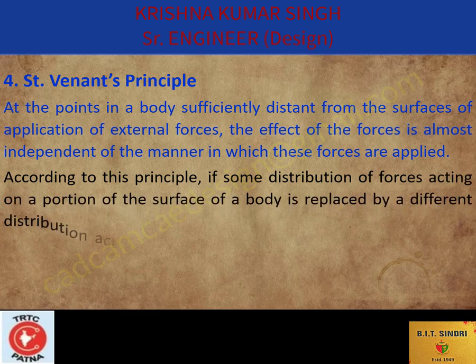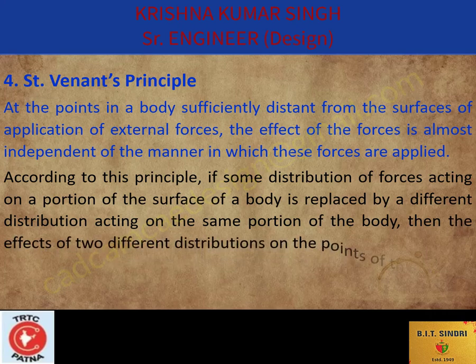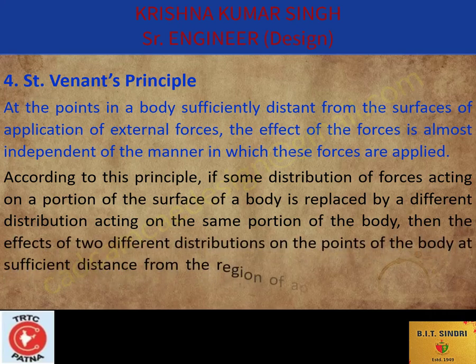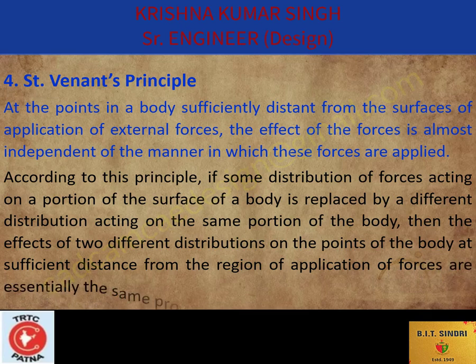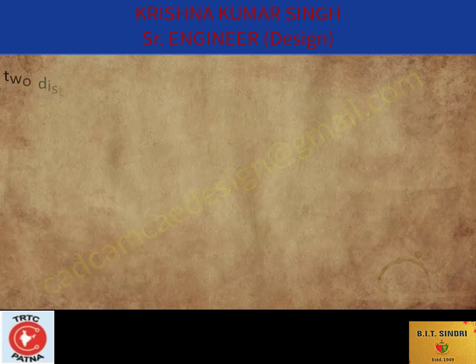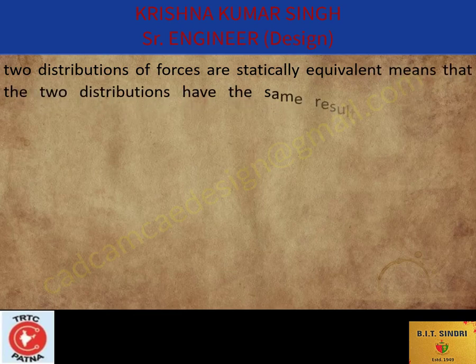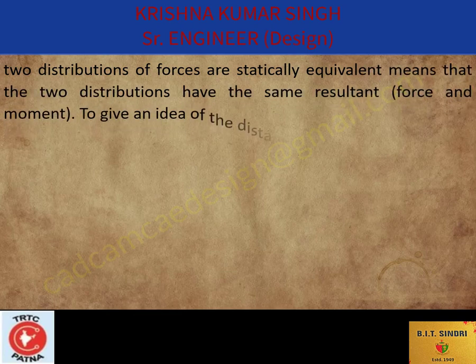According to this principle, if some distribution of force acting on a portion of the surface of a body is replaced by a different distribution acting on the same portion of the body, then the effects of the two different distributions on the points of the body at sufficient distance from the region of application of forces are essentially the same, provided that the two distributions of forces are statically equivalent,